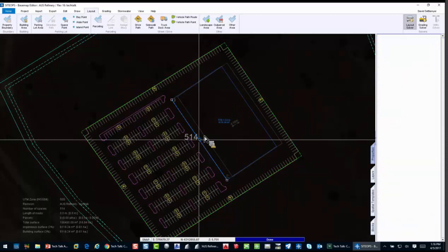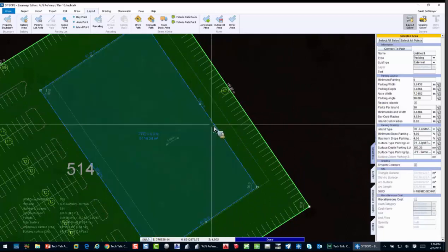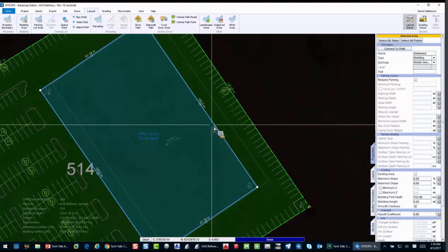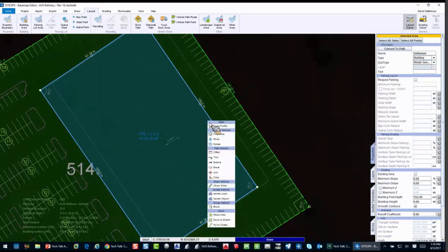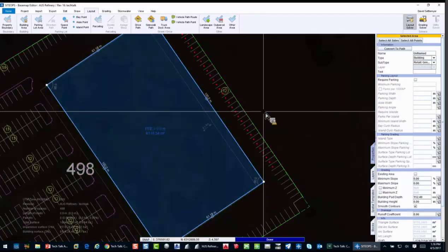Now, well, something happened, and this is a really cool thing as well. When you're using intelligent software similar to SITEOPS that we don't get in other CAD tools, and this is just sort of a byproduct, but it's really neat. I'm going to make an error happen. And y'all should see red dots in the parking spaces. This actually has the ability to go in and say, you know what, you've got enough room for a space, but you do not meet your drive aisle requirements.